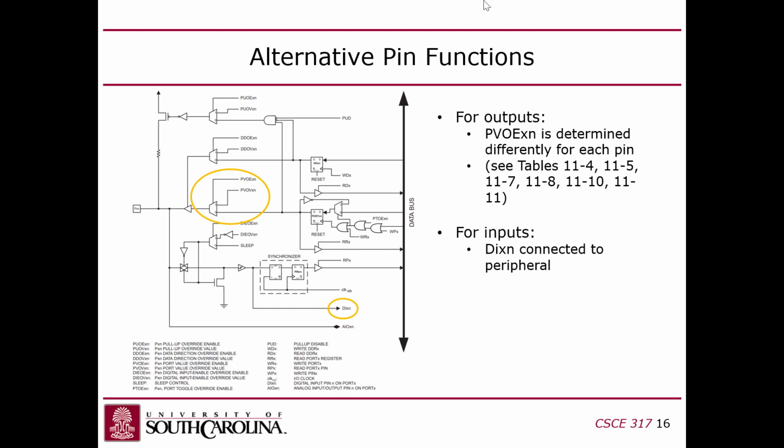But you notice they've got these muxes and these tri-state buffers, meaning you can turn on or off these paths, which eventually lead out to the pin, depending on what you want to do with the pin. In other words, they're reconfigurable. They're a lot like user I/O pins on an FPGA.